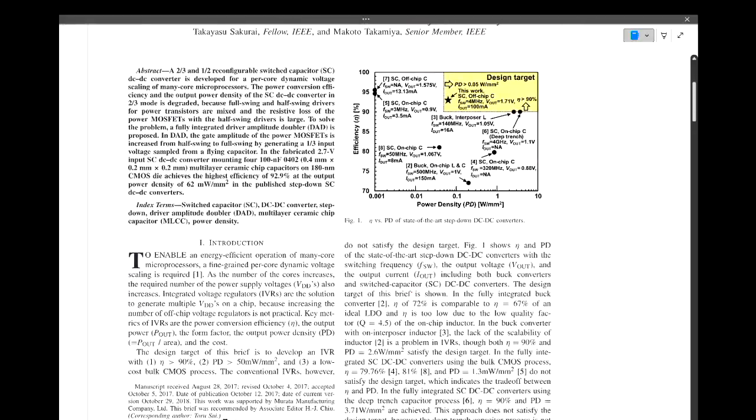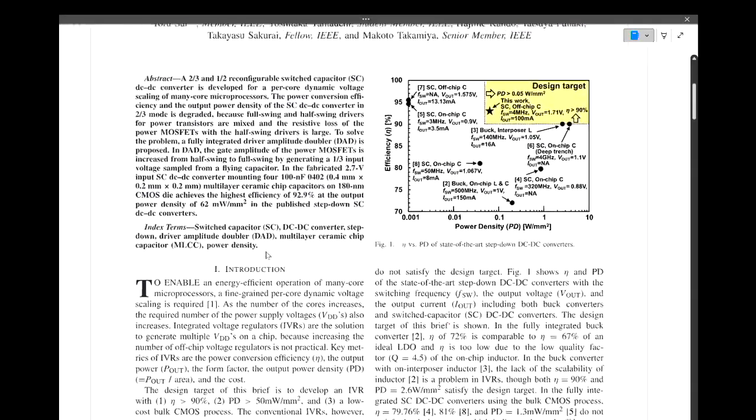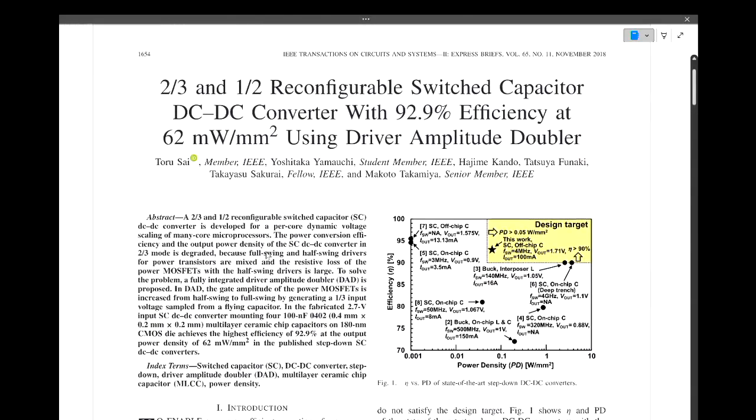But during phi 2 it's all disconnected. No, during phi 2 you connect it there and there, the second one. So during phi 1 you connect the capacitor up here, and during phi 2 you connect the capacitor up like that.